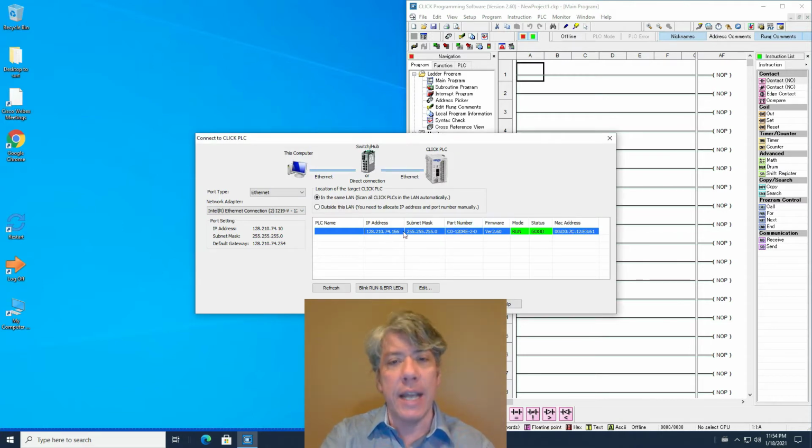You'll notice that it's actually connected via Ethernet. So honestly, the PLC is not really connected to that machine. It's connected to Ethernet, but that machine already has all of this information, like the IP address and the subnet and all of these things, so that the instructor station is set up to talk to that PLC. Now you could, in theory, log into any machine in that room, and I guess if you knew how, you could talk to this PLC even from your home computer. I don't know how that would work. I think you have to be on the same subnet mask.